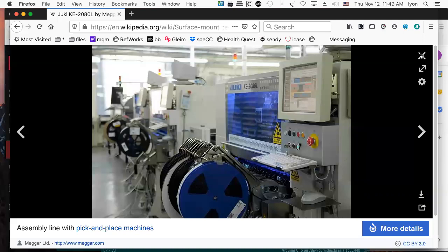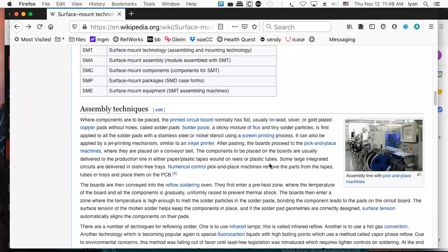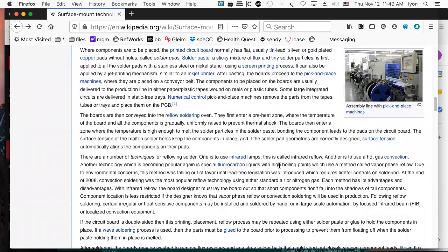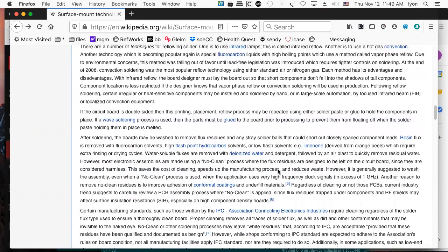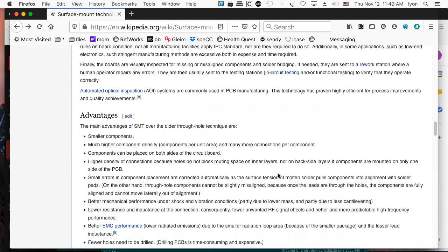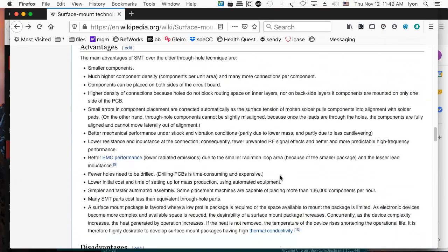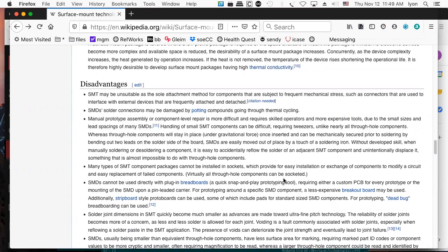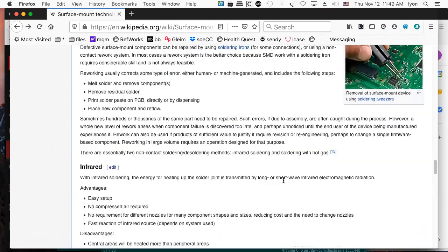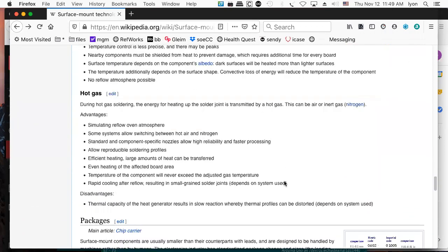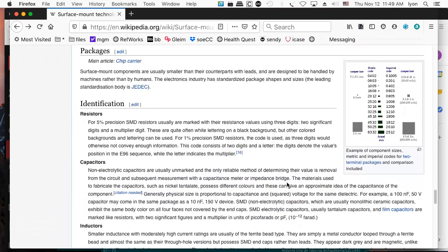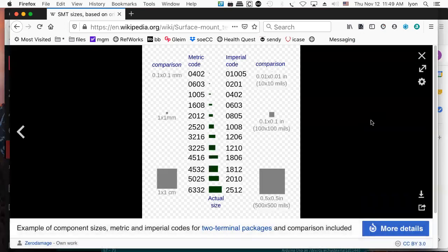What method did you use anyway? You just sort of set things up properly? Well, I marked an old breadboard with where to stick the pin headers in, so I could just stick pin headers in a breadboard and then set the board right on top of it. Yep, that's the way to do it. It saved a lot of time figuring out where they go every time and getting it set up, so I could get them set up in a quick second and then just start soldering.